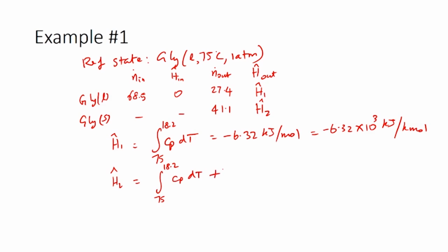So, the next step is only phase change happening at 18.2 degrees Celsius. So, this would be dependent on the heat of fusion. Heat of fusion by definition is, for solids to form liquids, the change in enthalpy associated with phase change when solids actually melt to form liquids. So, here we have the other way around, where liquid is being solidified to form solids. So, here is a freezing process, which means the specific enthalpy change would be negative of heat of fusion.